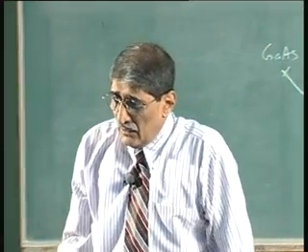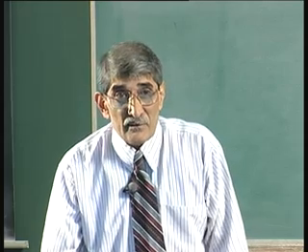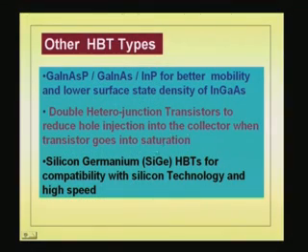So, that is why I thought I would point this out to you, because this is something people have been exploring. But if you are working on emitter coupled logic circuits, you do not have to worry about that, because there is no forward bias on the collector base junction, there is no saturation, it is only active. Still, you can make use of this without using ECL, for high speed devices. So, you can see that bipolar, the HBT, is a potential candidate for high speed devices.